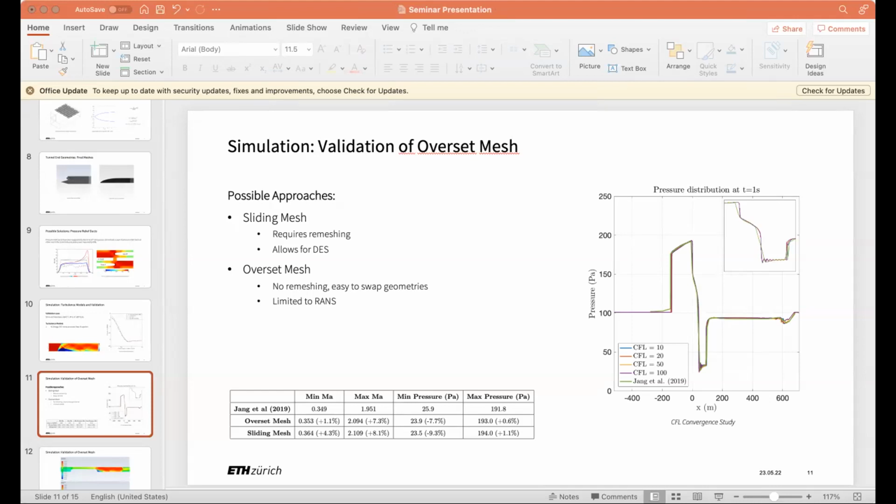that flow that's essentially at Mach 1. It's the exact same speed that you would have in a rocket. It's choked flow. You want to expand that as efficiently as possible to sort of atmospheric conditions. They're not really atmospheric, but they're atmospheric for the tunnel. And actually, if you think about it, it's kind of an inverted rocket engine. It's not a rocket, but the rocket is the surrounding tunnel, if that makes sense. Yes, yes.